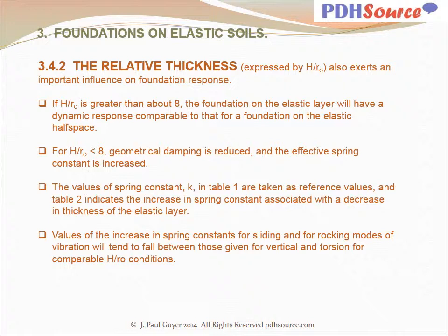Values of the increase in spring constants for sliding and for rocking modes of vibration will tend to fall between those given for vertical and torsion for comparable H divided by r_o conditions.